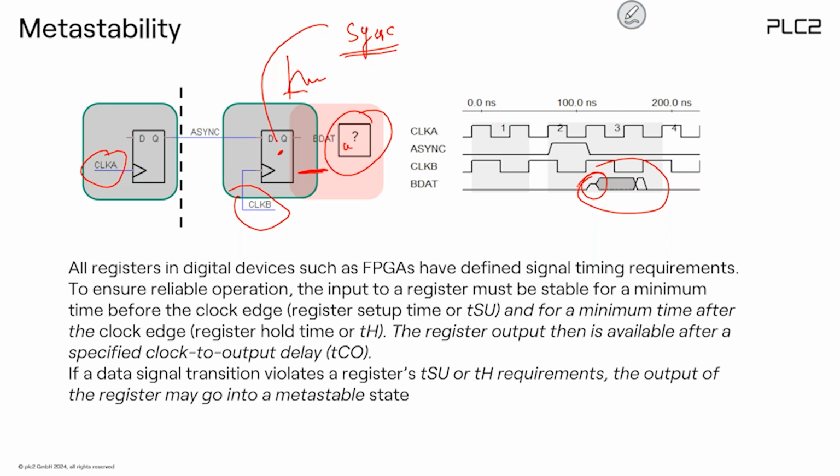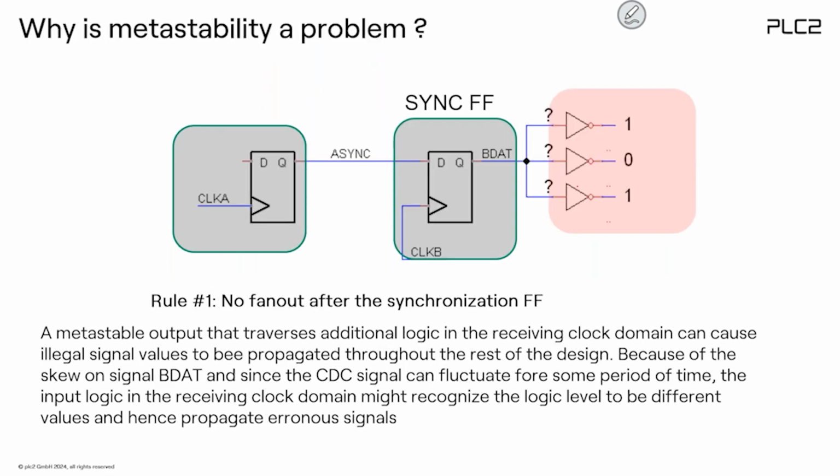When there is a violation, you will get this ringing, with a certain probability. That's a very, very big problem. The first rule: never take this signal from the sync flip-flop and use it at a different location. Never do this, because of this ringing.